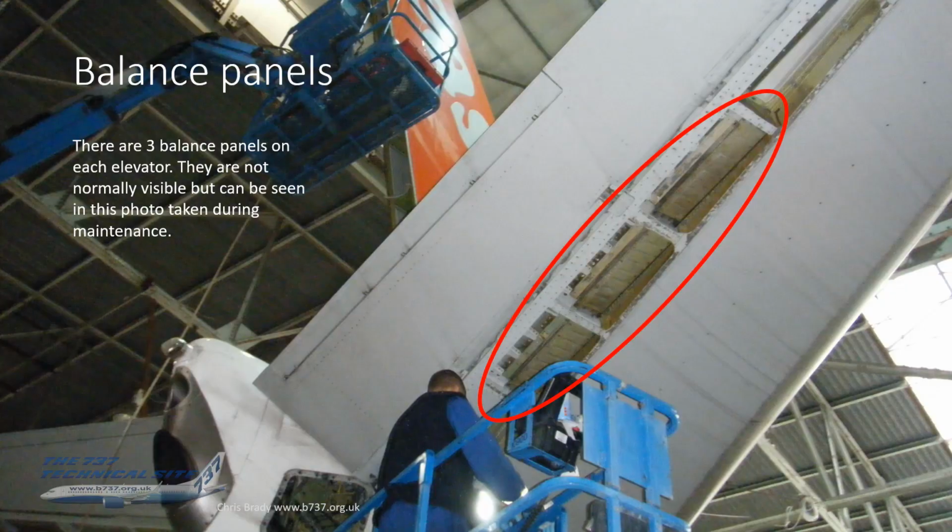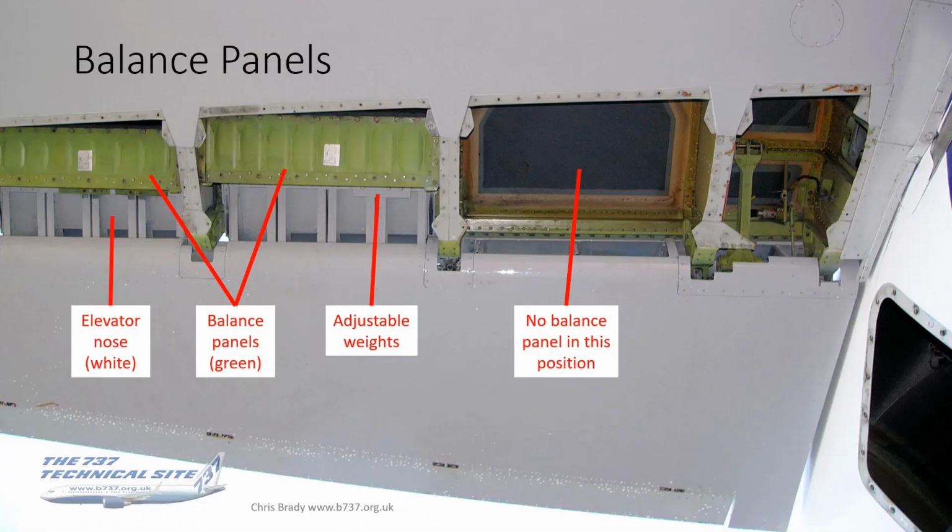And I'll show you a better photograph now, taken from directly underneath. You can see the left 2 panels there. You've got the balance panels in green, and the white parts there are actually the extension of the elevator, the elevator nose, if you will. So that's where they connect. You can just about see some little rectangle shapes, a couple of green ones on the left and a white one on there. They're the adjustable weights.